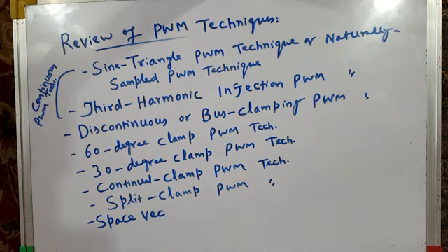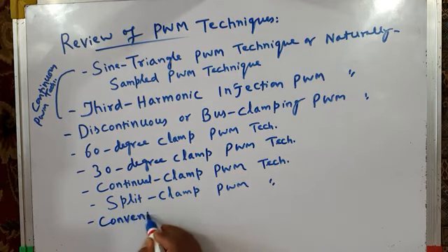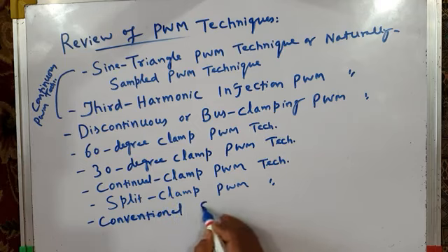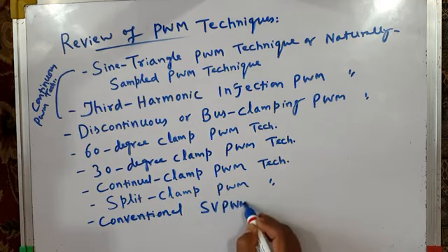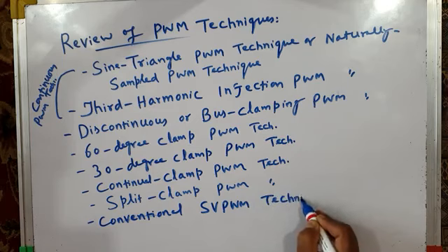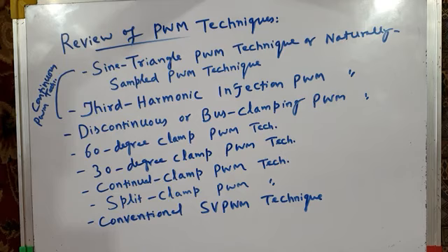In fact, I should write here conventional space vector PWM technique. We discussed conventional space vector SV PWM technique. Instead of having three sinusoidal modulating waves or non-sinusoidal modulating waves and comparing them with a high frequency common triangular carrier wave and generating the gating pulses of inverter and producing three-phase inverter output voltages, what we did, we synthesized